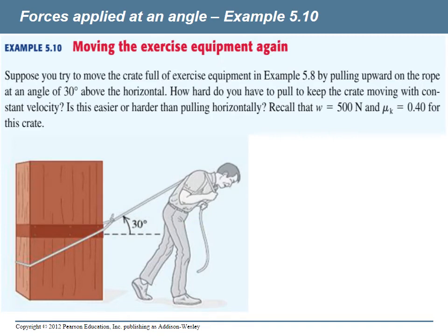But now that we've introduced friction, it changes the game a little bit, right? Because friction depends on some coefficient of friction, which they actually give us. The coefficient of kinetic friction is 0.4. And so the frictional force that's resisting motion here is 0.4 times the normal force.